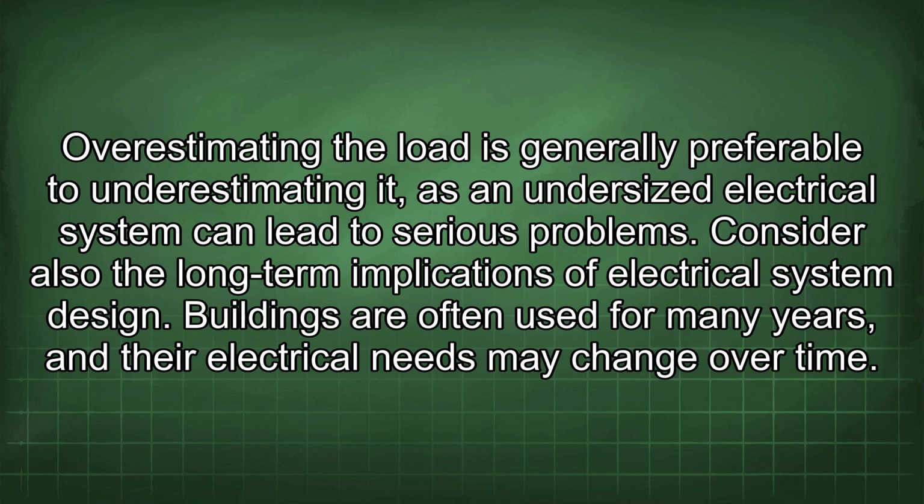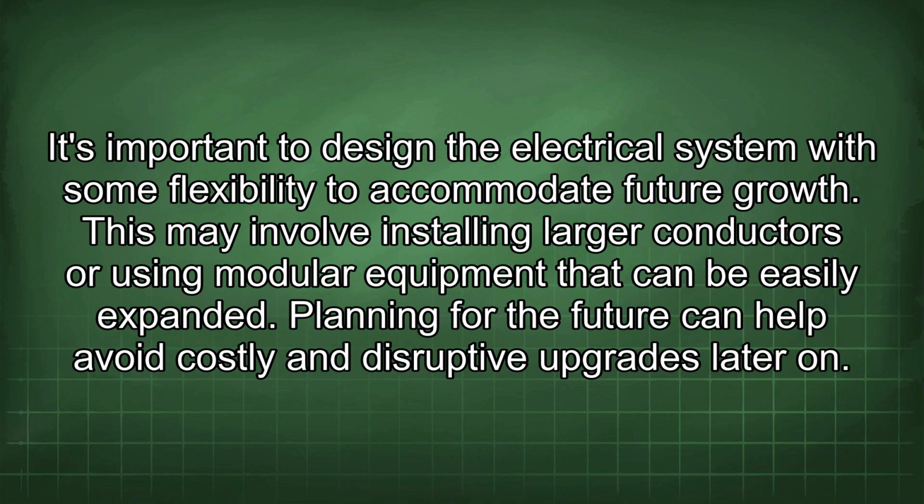Consider also the long-term implications of electrical system design. Buildings are often used for many years, and their electrical needs may change over time. It's important to design the electrical system with some flexibility to accommodate future growth. This may involve installing larger conductors or using modular equipment that can be easily expanded. Planning for the future can help avoid costly and disruptive upgrades later on.